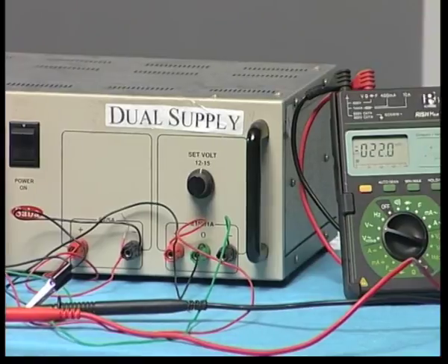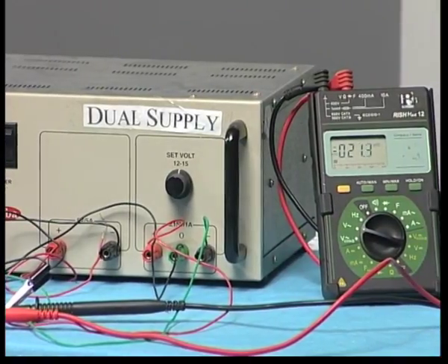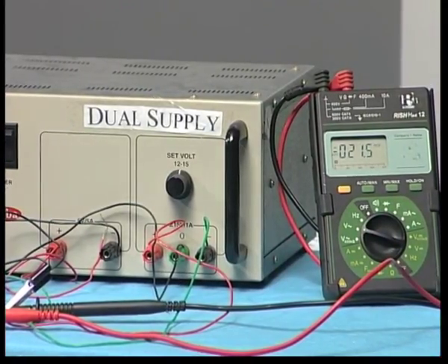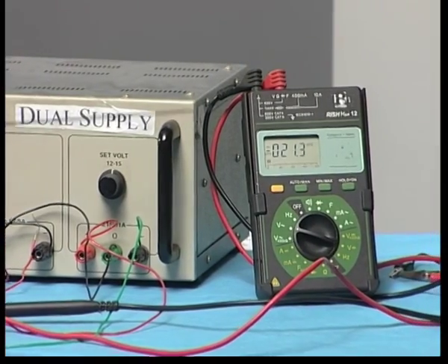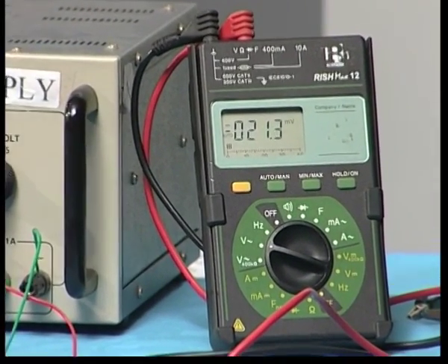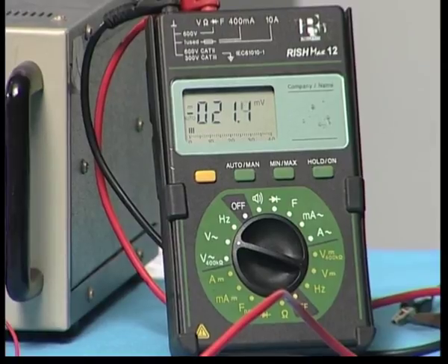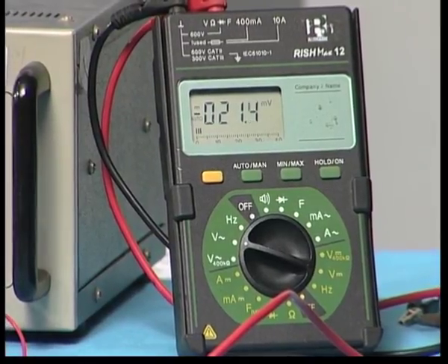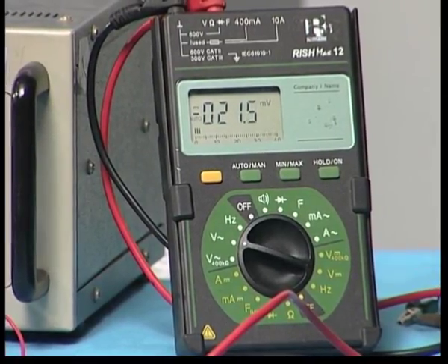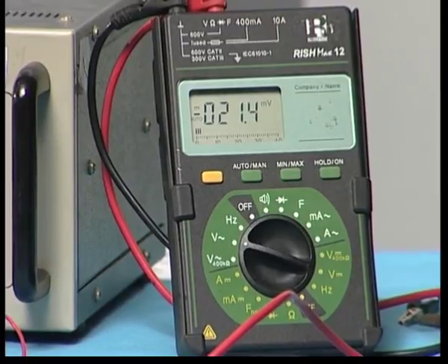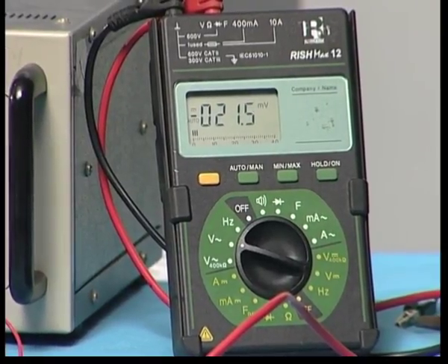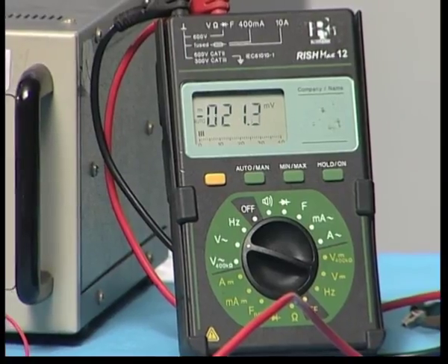So, what you get on the millivolts range is about 21.4. There is a slight variation, it is not perfectly 20, because this 10K resistor is what I read from the color code, but the actual resistance can be slightly different from 10K, maybe 9 point something or 11 point something. There is a 10% tolerance, and therefore it can be slightly different from 10K.